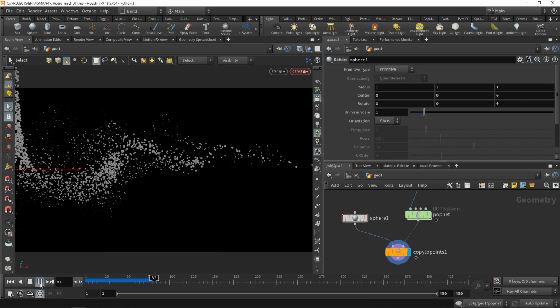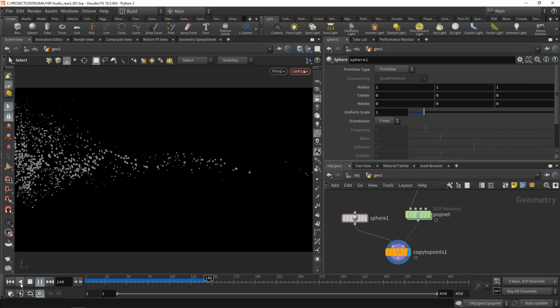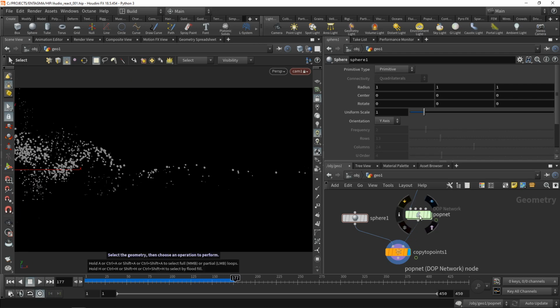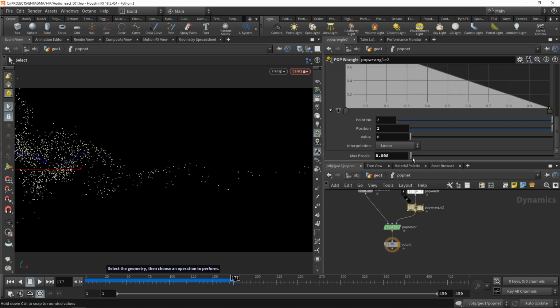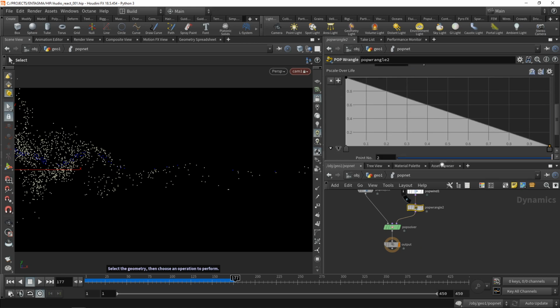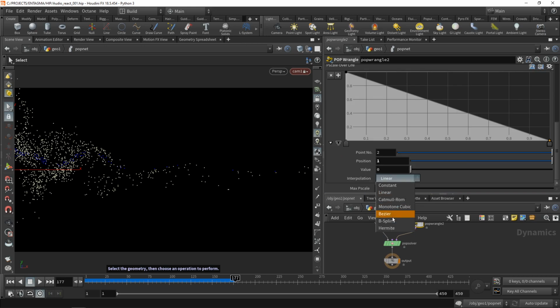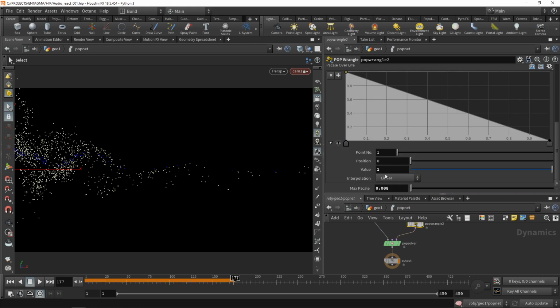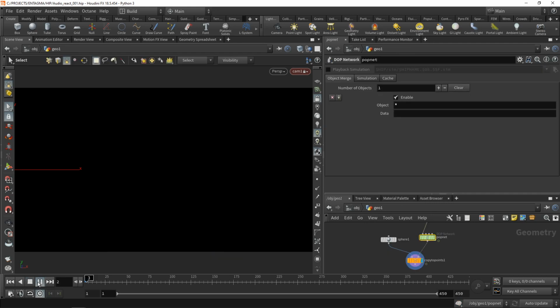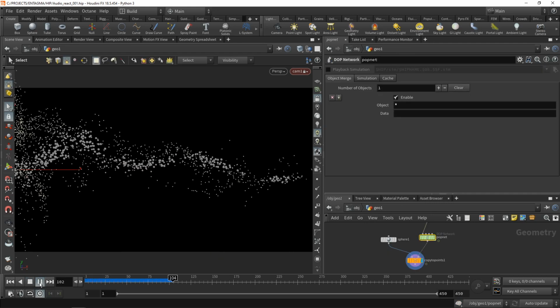And now you can see when those particles are being born, they are bigger and they scale down over their life. What I could do now is just go in here and dial in this exact curve because a linear fade usually doesn't look as good. And although this is a minute detail, let's just set those spline points to be B-splines. And let's add another point here like this, and maybe add another one here like this. Go back 1 level and let's just replay this animation. Yeah, and that's looking nice.